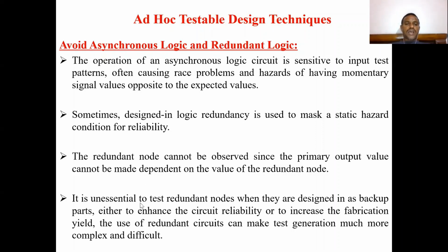It is unessential to test redundant nodes when they are designed in as backup parts, either to enhance the circuit reliability or to increase the fabrication yield. So only for reliability do we use these redundant logics. But testing cannot be applied to the redundant logic or redundant circuits because they cannot affect the output.